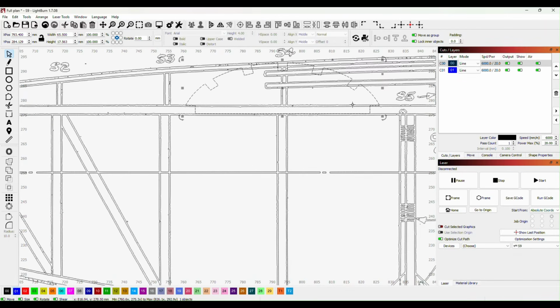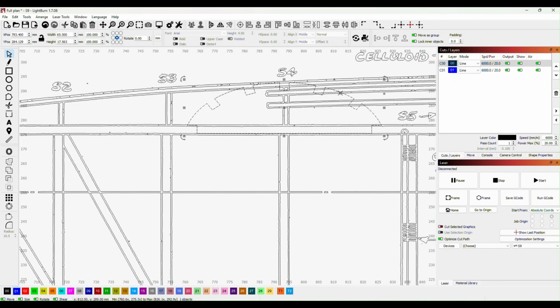Now what it will also do is, because it shrinks all over uniformly, it's going to do 2 things. It's going to slightly change the shape of our notches and change the size of the notches, but also it's now made us a little bit short of our 3.2 millimeters edge that's going to sit on the longerons.